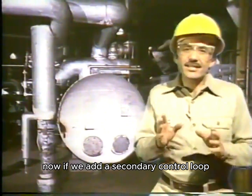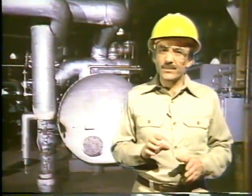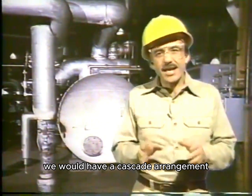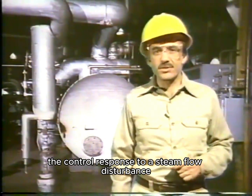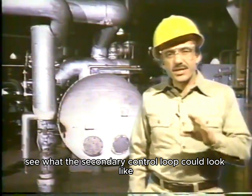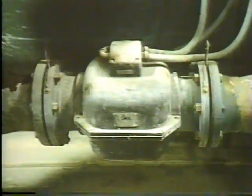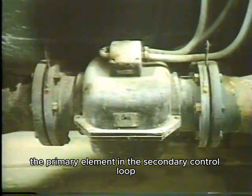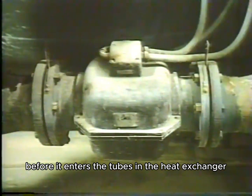Now, if we add a secondary control loop to the primary control loop that we just looked at, we would have a cascade arrangement that could improve the control response to a steam flow disturbance. Let's see what the secondary control loop could look like for this process. The primary element in the secondary control loop for this process monitors the flow of steam before it enters the tubes in the heat exchanger.